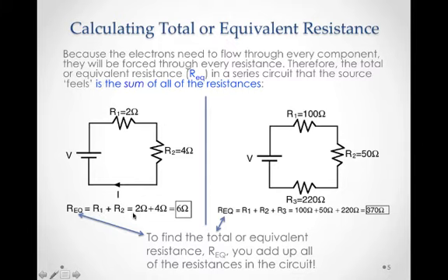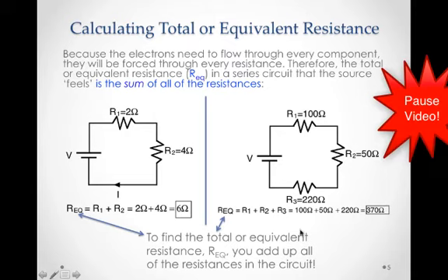in the circuit. So another example over here, again, easy to flow to this point. Feel 100 ohms of resistance there. Easy to flow here. Feel another 50 ohms for a total of 150. Easy to flow here. And then another 220 ohms and then we're back. So if you add them all up, 370 ohms would be the equivalent or total resistance.